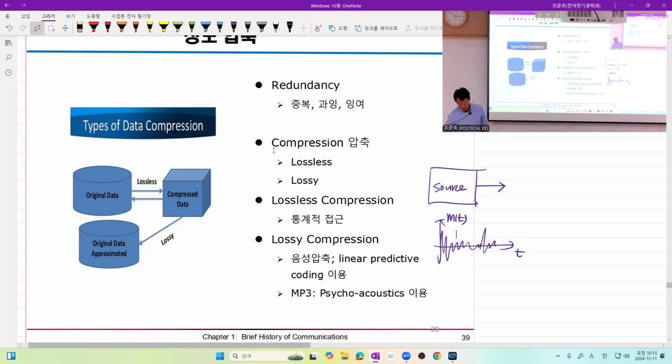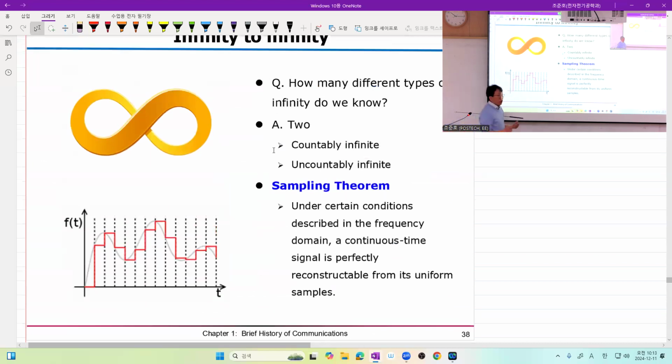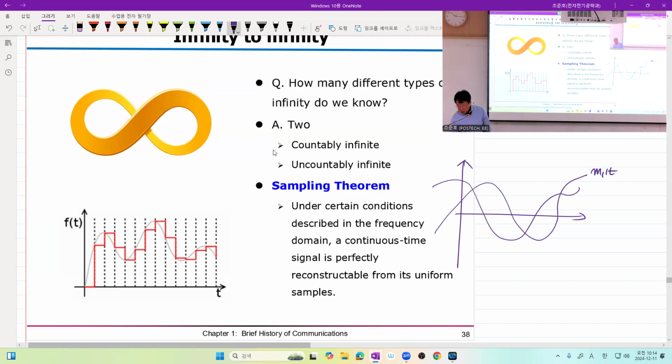And if we just do the quantization, we have two problems. The first one is that our sampling rate may introduce some degradation in our conversion from analog signal to digital signal. For example, as you learned in signals and systems, suppose you have two different signals, M1 of t and M2 of t. But suppose you sample here and here, these 3 points, even though this is not uniform sampling, can you distinguish these two signals? Some information in between two consecutive sampling instants may be lost, right?